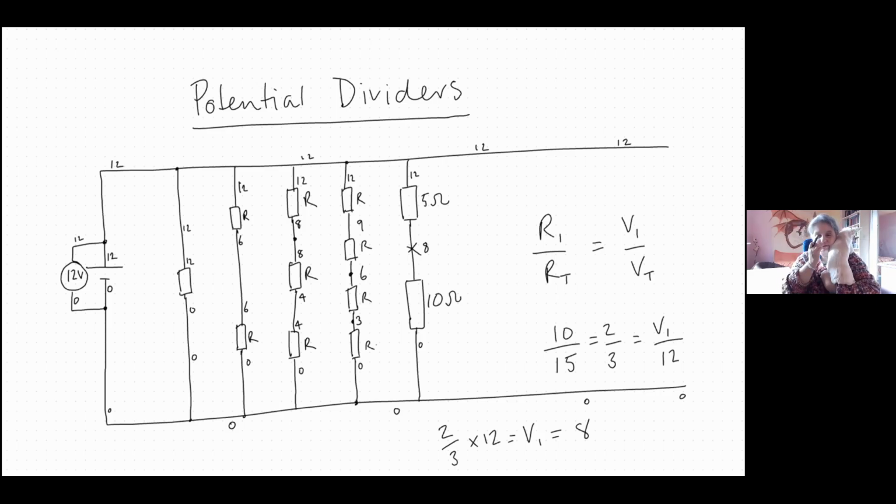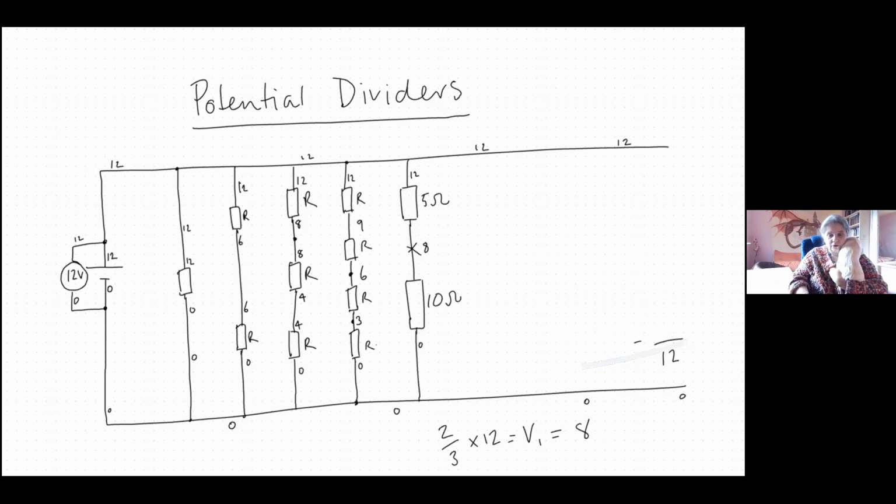Anyway, right, okay. So now we are going to do a few more like this. Everybody makes it so complicated. All it is, is the same fraction for the voltage as it is for the resistances. That's all it is. Right, so we're going to have a resistor and a motor this time.